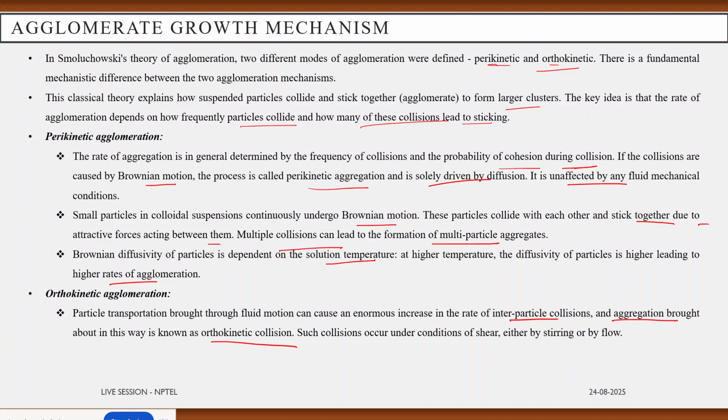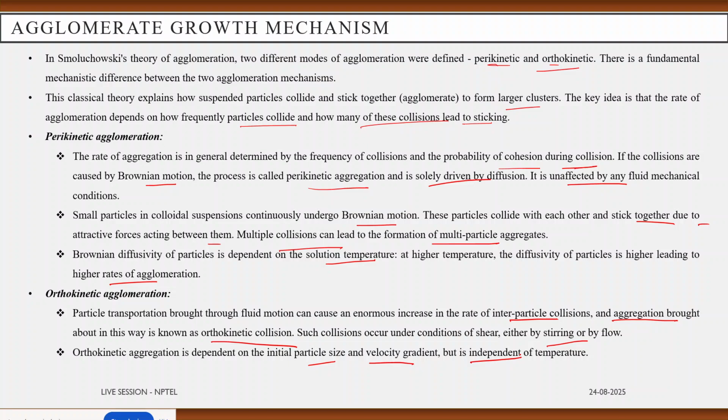Such collisions occur under conditions of high shear rate, and this can be either by stirring or any kind of high shear flow. So this orthokinetic aggregation is dependent on the initial particle size and the velocity gradient, but it is independent of temperature.